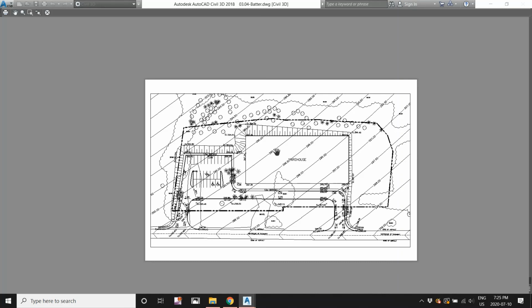So download the AutoCAD file for this lesson and try using the sloping LSP routine, the batter command I mean. So remember, you have to load it using appload, and then you type batter to use it, and you can play around with the interval in there.